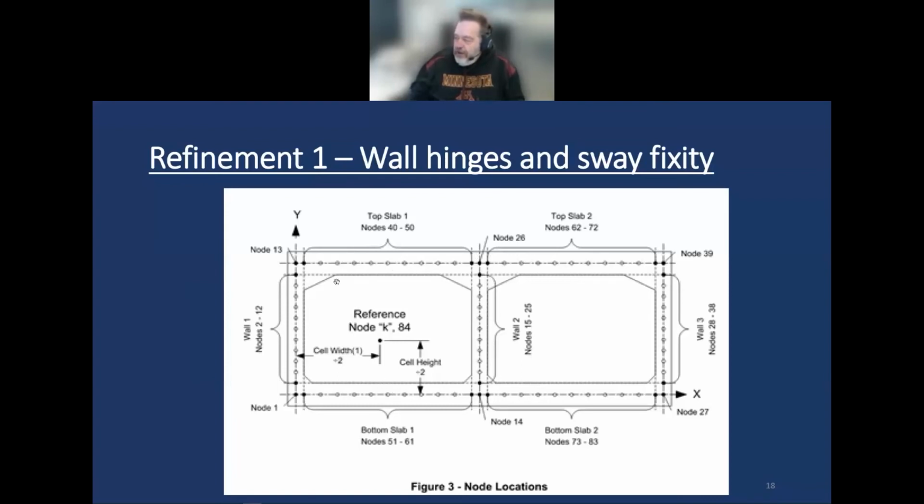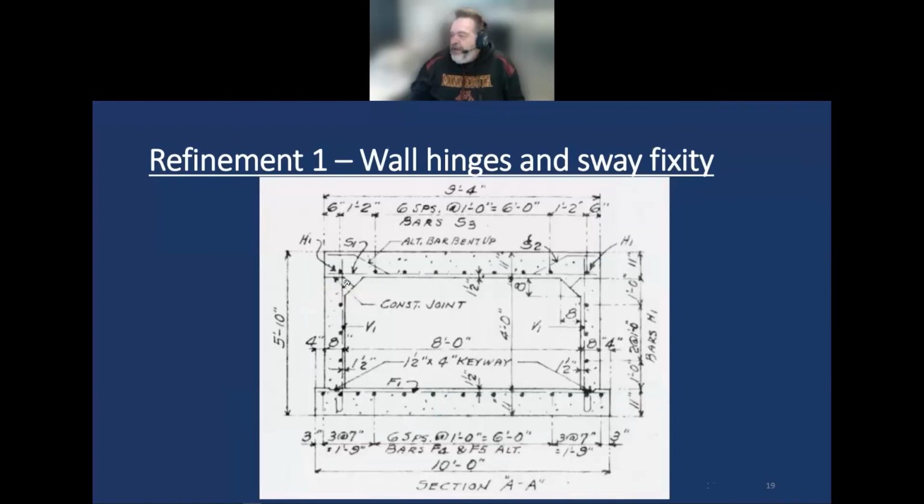If you've got a W section, you need to be able to force it into a positive moment only situation. So you need to put hinges at the top of those walls. Here's a single cell W section, and here's that construction joint through the haunch at 45 degrees.